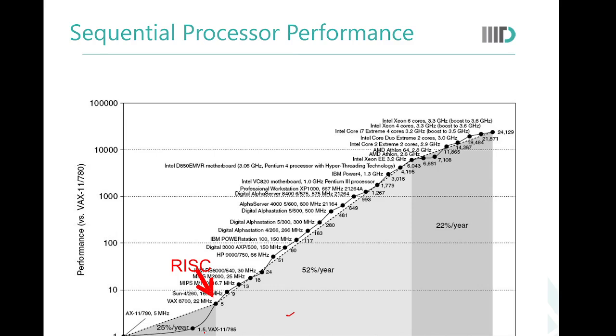They have the same number of operands, take the same number of bits to be represented, and so on. Because of this uniformity, you can design your hardware very efficiently, and that is why there is a significant performance improvement once RISC was introduced.